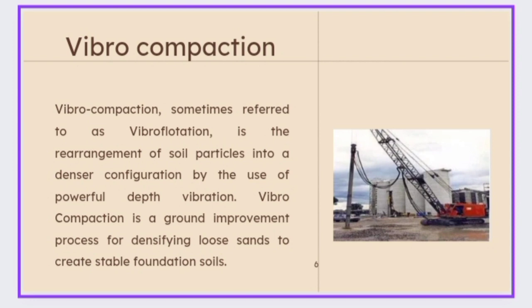Vibrocompaction, sometimes referred to as vibroflotation, is the rearrangement of soil particles into a denser configuration by the use of powerful depth vibration. It is a ground improvement process for densifying loose sands to create stable foundation soils.